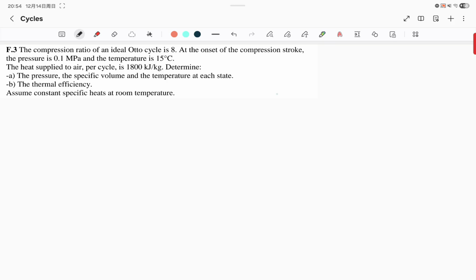And then for the Brayton cycle, which uses ideal gas, you can use the ideal gas law, PV equals mRT. You can use isentropic relationship equations. You can also replace your delta H by Cp delta T, because the prerequisite of using this is just that you're going to have ideal gas.